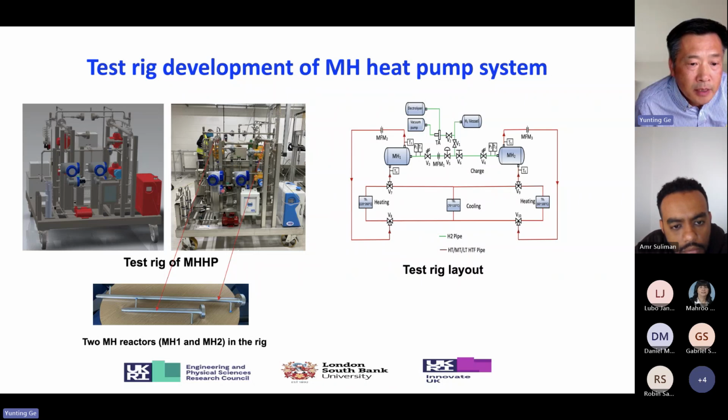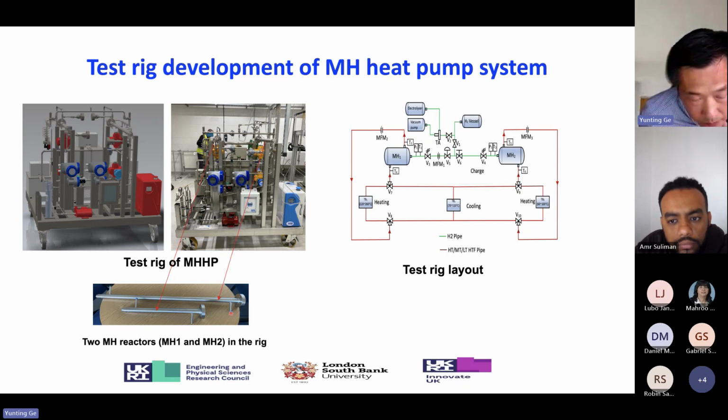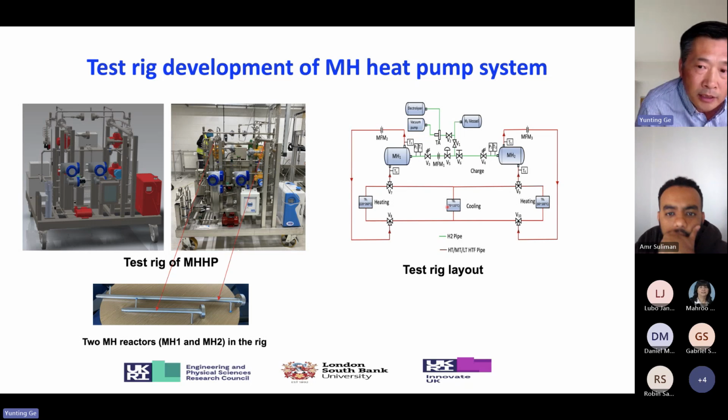You can also see the heat transfer fluid pipe connection ports, which connect to the heat transfer fluid. We utilize thermal oil as the heat transfer fluid to simulate the high temperature heat source, the low temperature heat source, and also the medium temperature heat sink. We're using 3 thermostatic baths here. One is for heating, another for low temperature heating, and in the middle is the heat output for the heat sink.